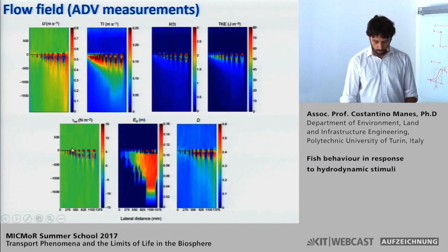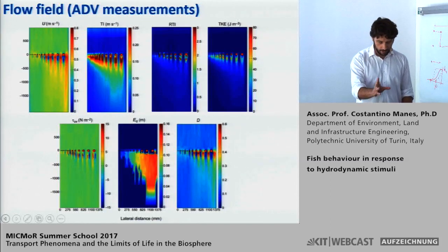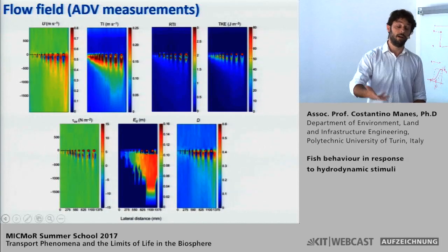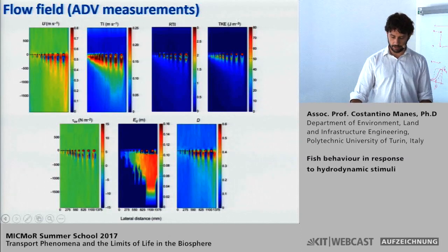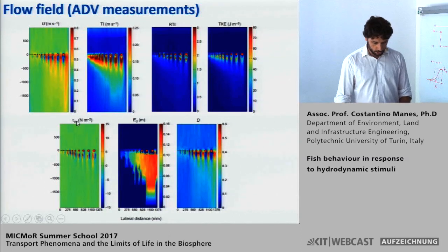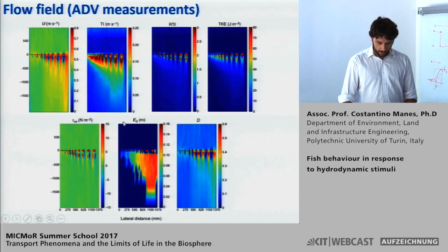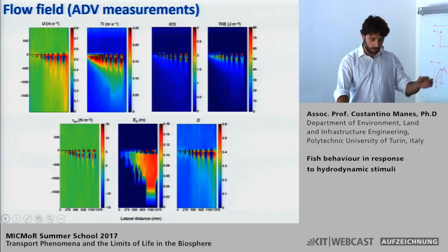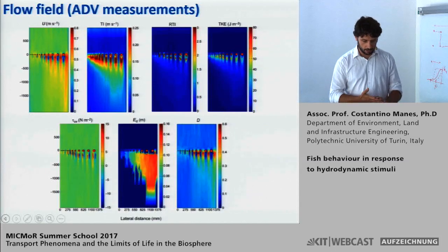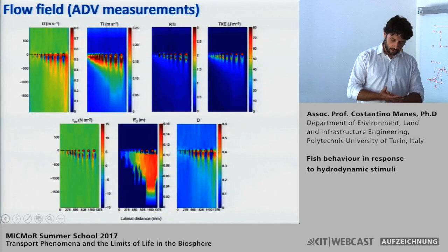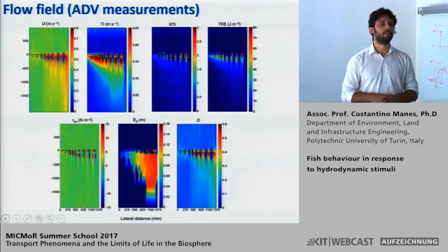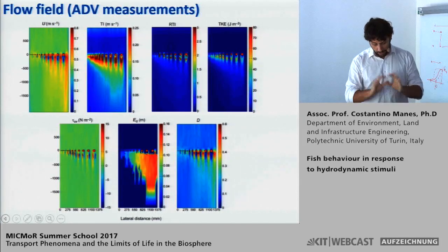We have chosen to address these turbulence metrics because these are those that were investigated in the past literature. So, the turbulent shear stress, and the eddy size that we have been estimating using 2-point correlations. We didn't trust the Taylor hypothesis within the near wake zone, so we could estimate the size of the eddies